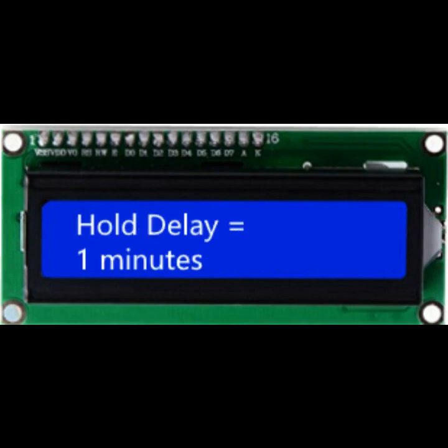Hold delay. Hold delay is the amount of time that the alarm input will be ignored after a unit is started by the ACO. This is to give the unit time to stabilize after starting. This does not apply to the loss of power input.